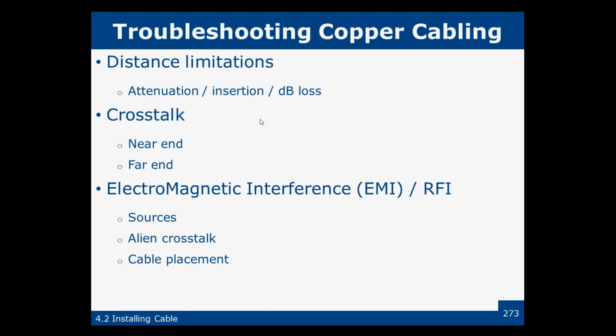This one I didn't do, so I'm going to tell you the answer. What is the reason for making power sum crosstalk measurements when testing a link? Power sum measurements are used when you use all 4 pairs, as gigabit and 10 gigabit Ethernet do. Which cable types are made of a solid core of copper surrounded by insulation, by braided shielding, and an outer cover?